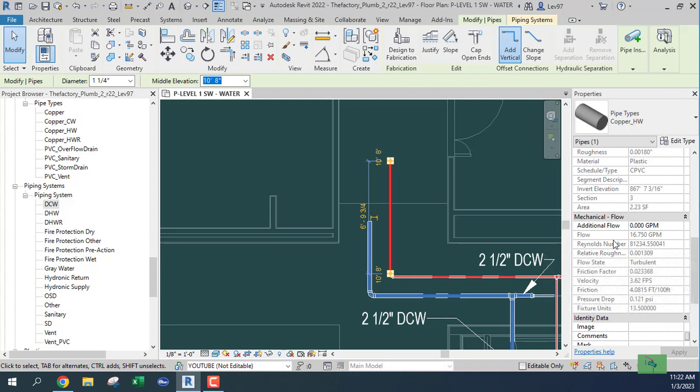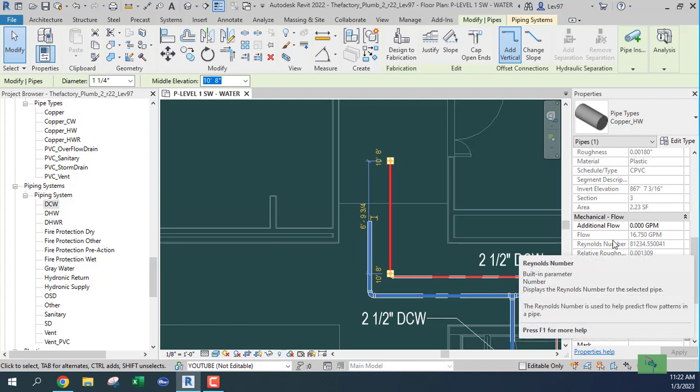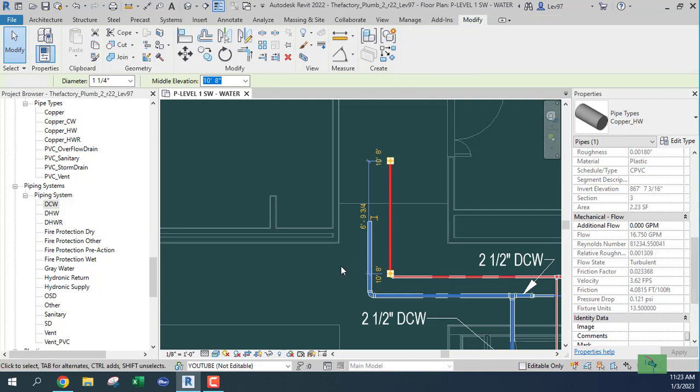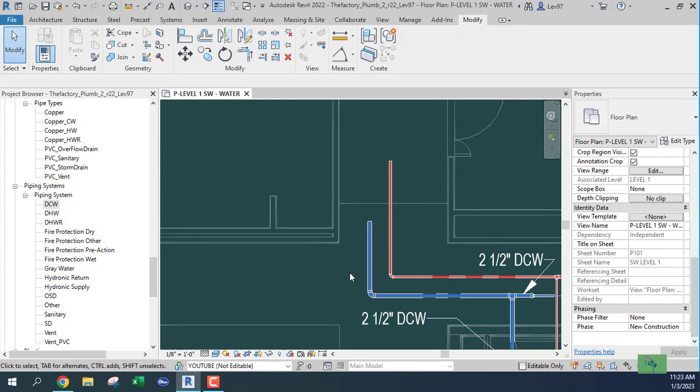So if you look at our table in the conversion of fixture units to equivalent GPM, 13.5 fixture units or 14 will produce, for flush tanks, 11 GPM, which is just 6 GPM off of what Revit is giving to us, okay? So it's not exact. So what I'm assuming is that at this point, Revit is following Hunter curves on the cold water side.